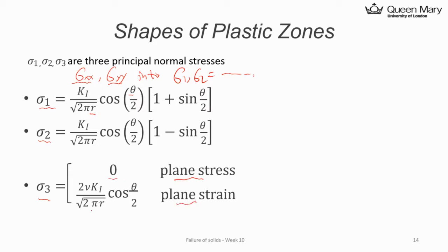For plane strain, it's slightly different, because we have this relationship sigma 3 equals the Poisson ratio times sigma 1 plus sigma 2. Okay, that is something I have derived before, so you can watch the lecture note from the previous slides. You get this equation. Just to remind you, it's just written as the strain, 1 over E, for example, this is epsilon 1 equals sigma 1 and there's some Poisson ratio times sigma 2, and the Poisson ratio times sigma 3, okay.